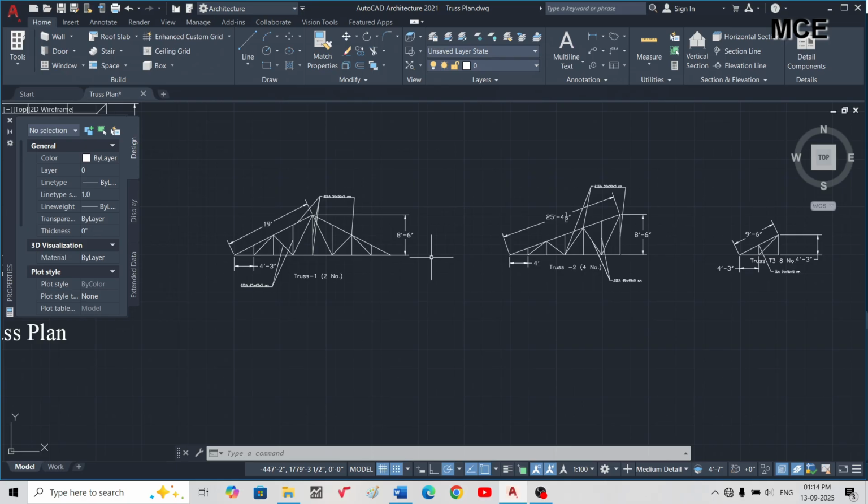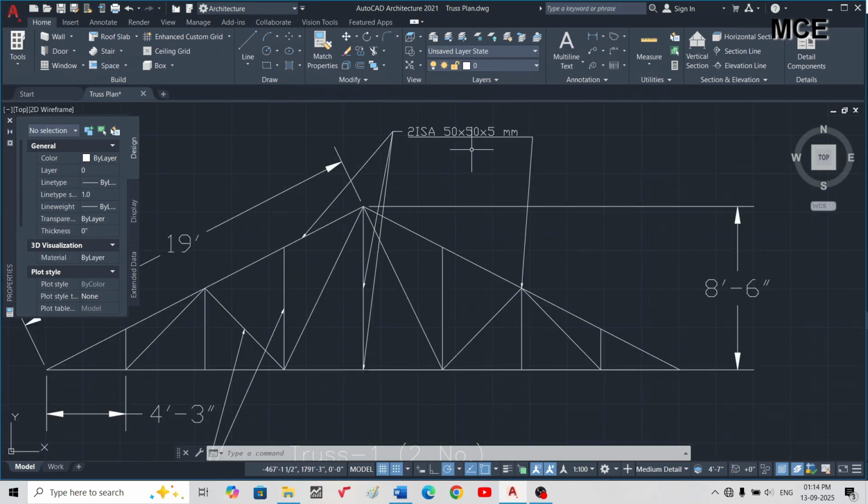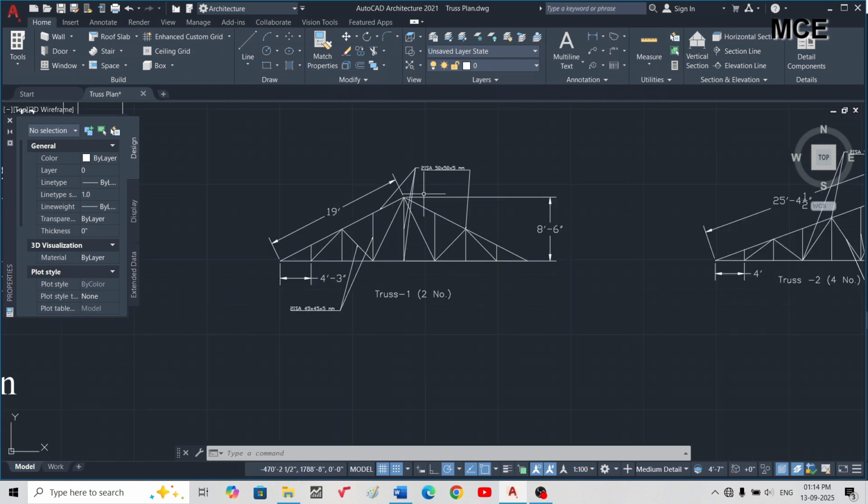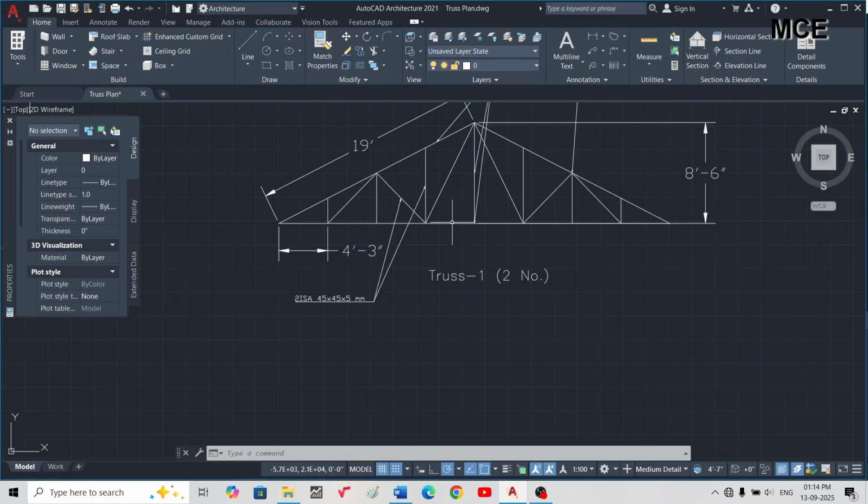Okay, or if you are an experienced civil engineer, you can know what type of section will be suitable in my area. If the loading is higher, you have to take the channel sections. Okay, but if loading is less, you can take the angle section or the hollow square sections. Okay, after designing these trusses, there are other 2 points which you have to take into consideration.